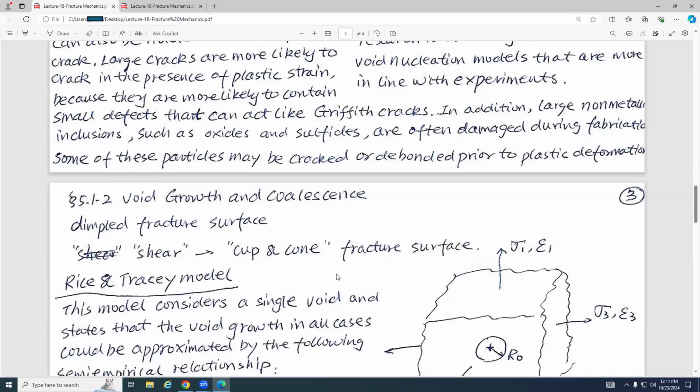If it is a central crack, the through-hole crack, this is 2a. If we have this kind of central crack in an infinite plate, then K_I equals sigma square root of pi a. Do you have a sense? Okay, so this is the midterm.